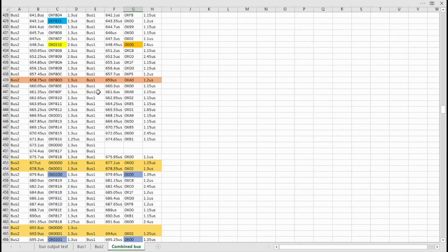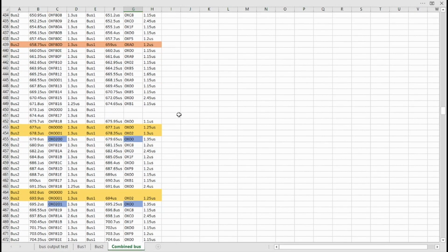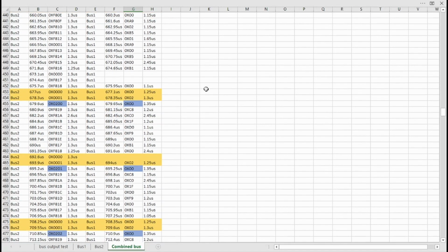So if we jump down to the second part of the program, we go through and we are doing just a read from the RAM now. So the reason why we're doing this read from the RAM is we want to make sure that the RAM has actually taken that information and stored it. Whereas before it wasn't going to do that because the RAM wasn't there. So as you saw, we set up our zero page. So in 00 we put 00, and in 0001 we put 02. So that gives us our pointer to memory address 0200, and we're just going to read from that pointer.